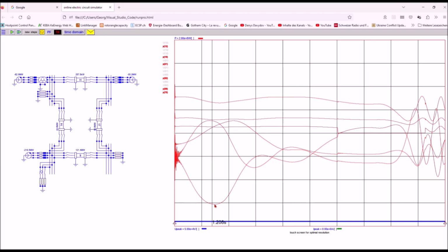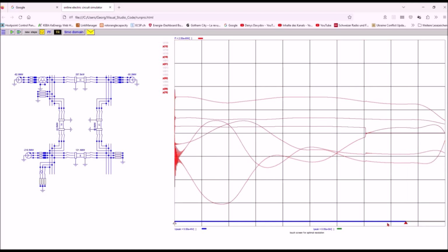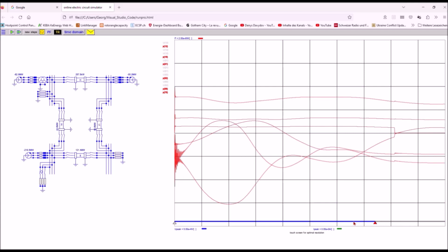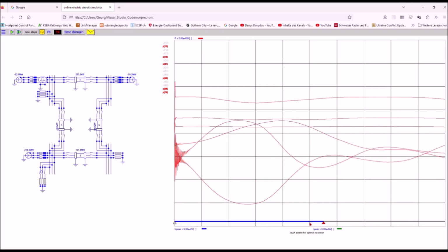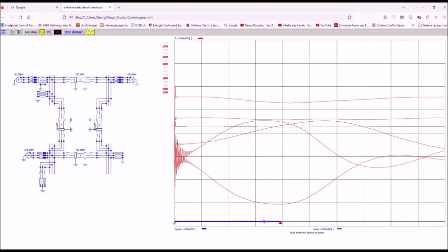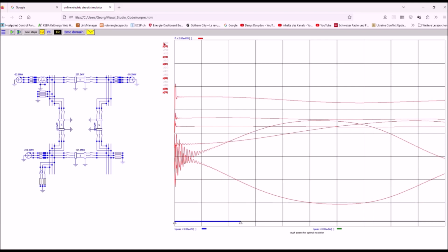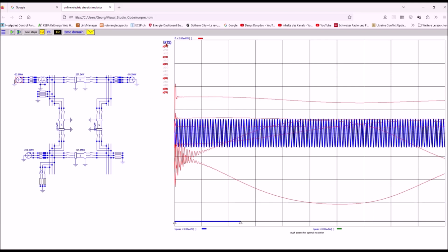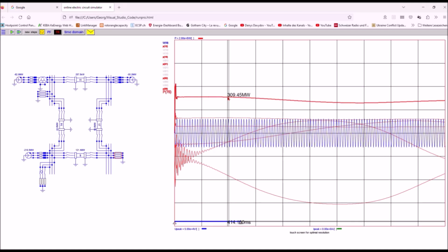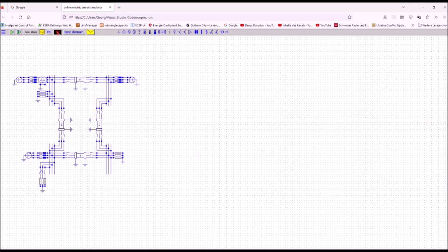Touching the curve highlights the corresponding element with a red square. With the cursors to the bottom left and right end of the screen, you can zoom in the area of interest. You can reactivate the hidden curve by clicking on the corresponding element of the list. And finally, you can remove the transient recorder screen by clicking on the transient recorder button.